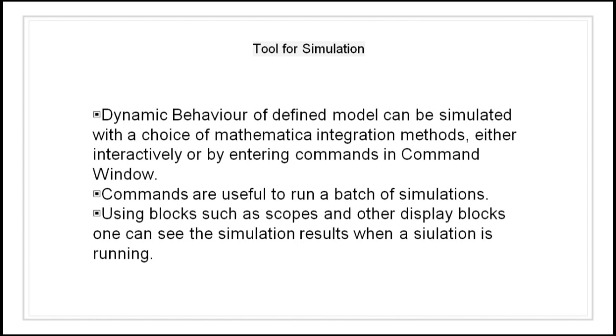Commands are particularly useful for running a batch of simulations. For example, if we are doing a Monte Carlo simulation or want to apply a parameter across a range of values, we can use Matlab scripts. Using scopes and other display blocks, we can see the simulation results while a simulation is executing. So we can change the parameters and see what happens. So for what-if exploration, we can save simulation results in the Matlab workspace for post-processing and visualization.